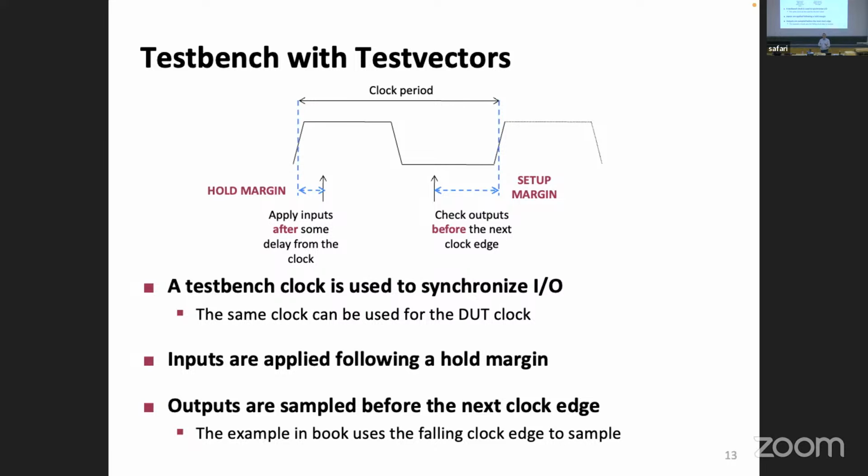I like it. What happens if you don't have this separation? You have this entire period of time where you can do something, and please don't do it here. What happens if I do it here? Bad things happen. The bad thing that can happen is if it happens exactly at the same time, it could be that this input comes before the clock is evaluated. So you could actually end up having the input that was meant for this clock edge get sampled from here. So this is the first problem.